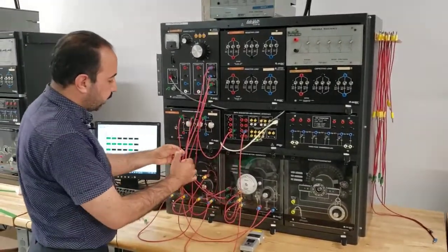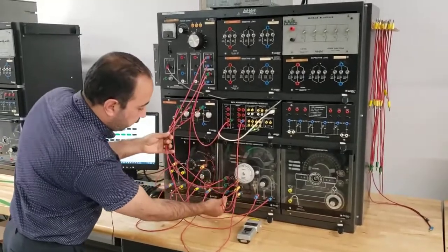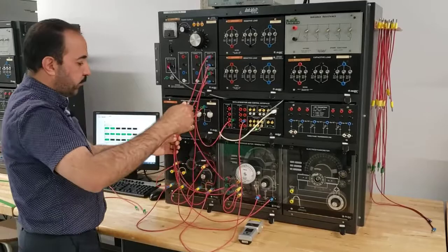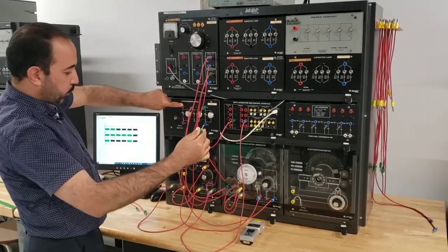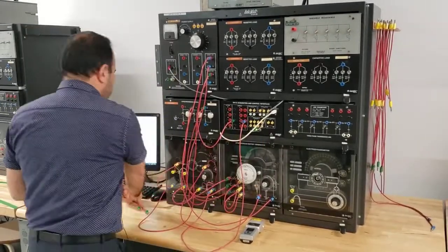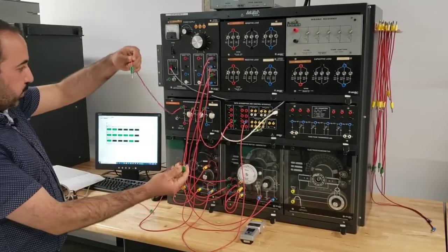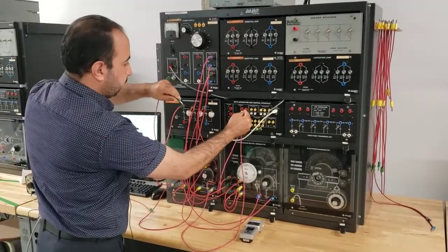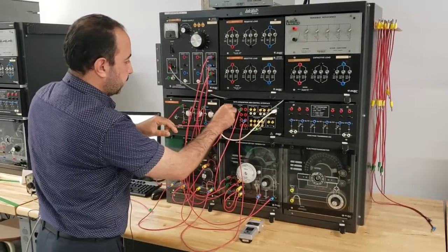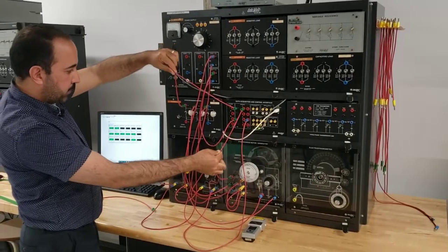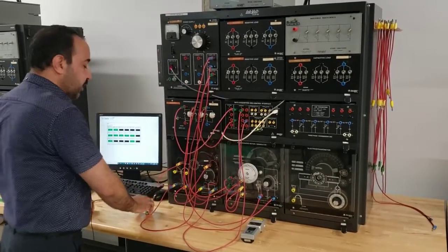So for measuring the armature current, I'm going to deal with one of these three. So I'm going to reconnect this guy again, because I would like to connect a meter between these 2 points. So I will bring another wire, and in between those, I'm going to connect this ammeter. So the current here is the armature current.